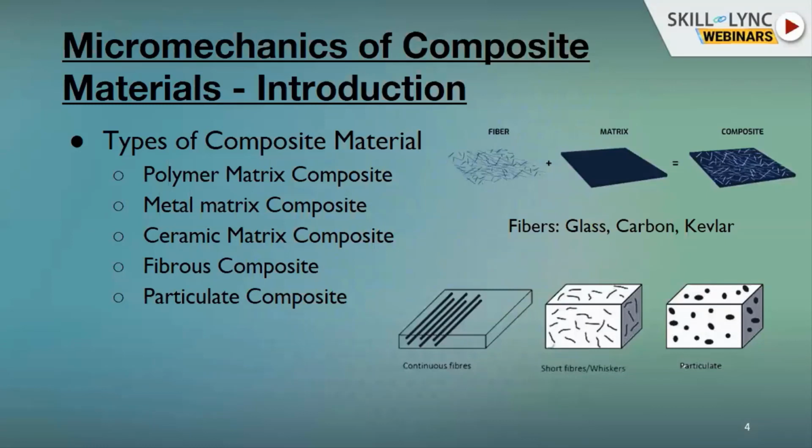When we speak of fibrous composites, these fibers are unidirectional, but they are not restricted to be in one direction. We can also have fibers in two directions. We call them bidirectional fibers, and then the weaving patterns will be different. So we have satin weaves, which form various types of directional properties.